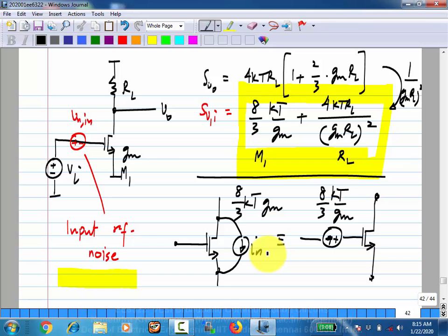But once you know the representation of noise, everything else is easy, in that it is just like small signal calculation from the noise source to the output, and then noise from different components are uncorrelated. You add up all the noise spectral densities, and then you can find the noise variance and so on. Any questions about any part of noise calculations we have done so far? Noise models or calculation? Yes.